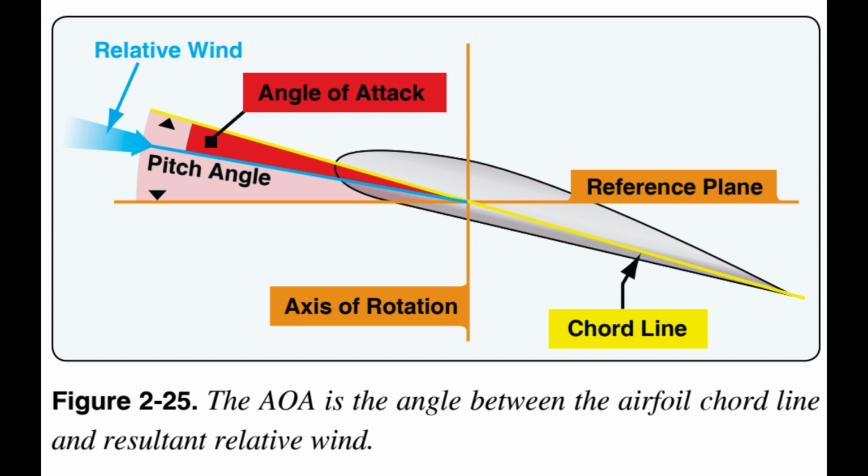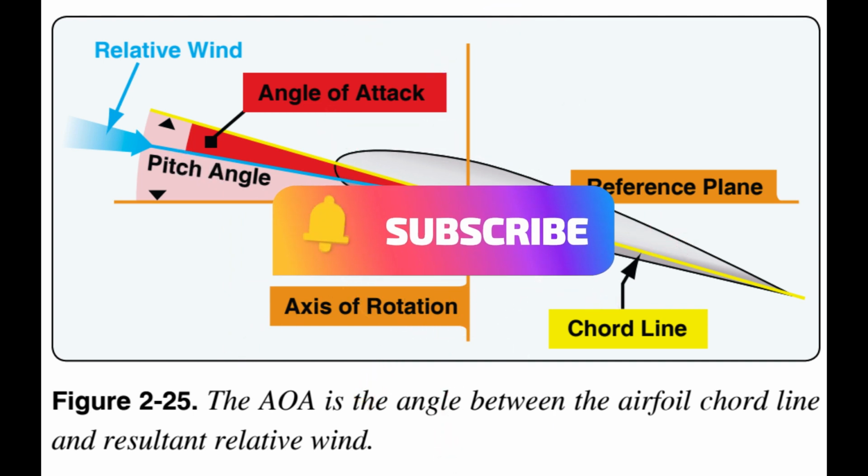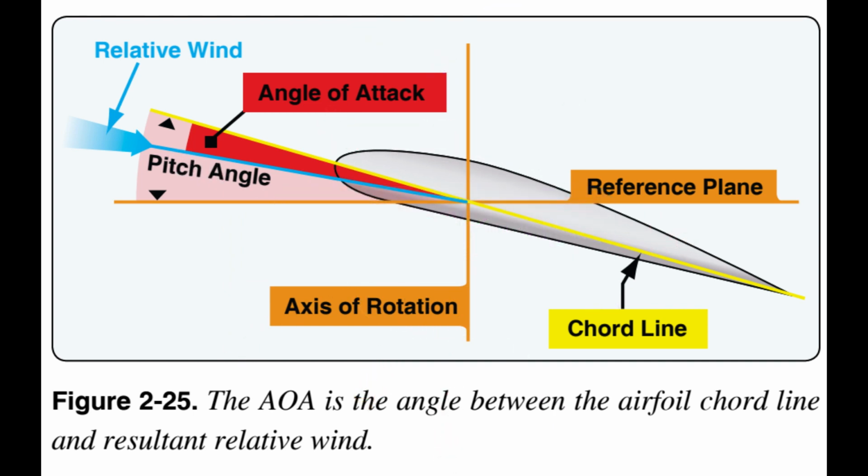It occurs in response to changes in lift due to changing velocity or cyclic feathering. No flapping occurs when the tip path plane is perpendicular to the mast. The flapping action alone, or along with cyclic feathering, controls dissymmetry of lift. Flapping is the primary means of compensating for dissymmetry of lift. Pilots adjust AOA through normal control manipulation of the pitch angle of the blades. If the pitch angle is increased, the AOA increases. If the pitch angle is reduced, the AOA is reduced.